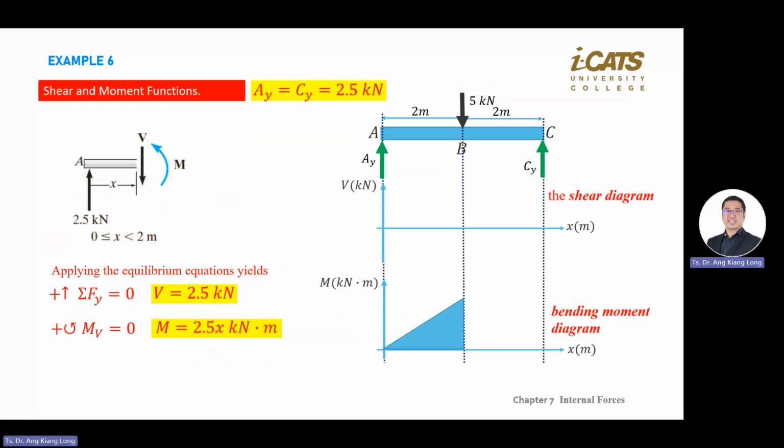As you can see, we are almost done already. The question is about 90% there. First step, do the analysis, cut at a certain x, set all the forces equal to 0 and all the moments equal to 0, and you will get what V is. Why V only?